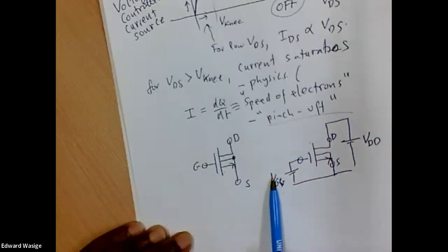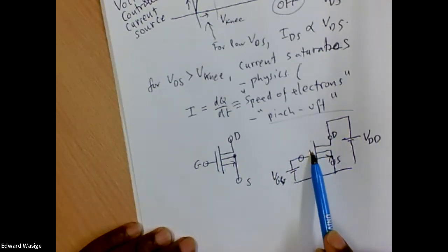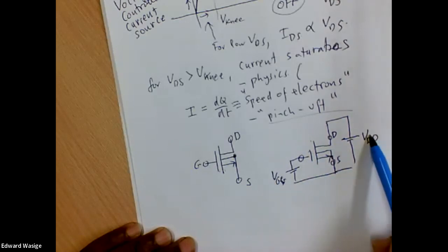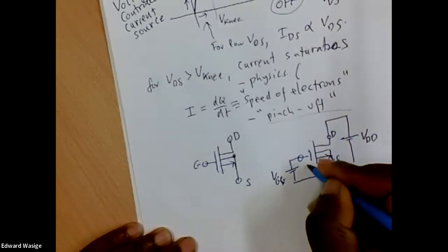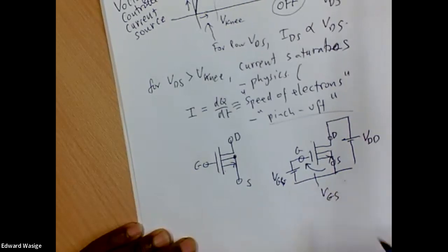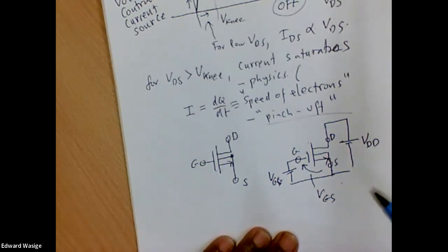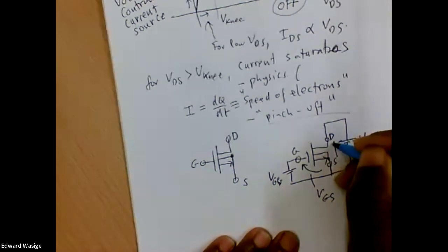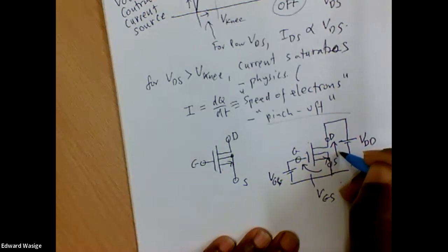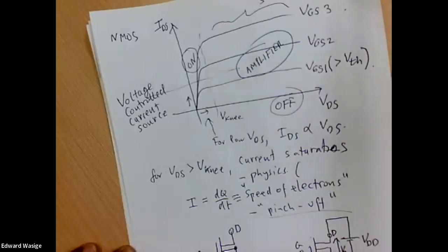So this is the gate, the voltage that we use to control whether the transistor is on or off, and the voltage that's used to determine the current that goes through. And across the transistor, I have my voltage VGS there. So in this particular case, the supply voltage VGG is the same as the gate to source voltage, and the supply voltage VDD is the same as the transistor voltage VDS. And if we plot them, it looks something like that.